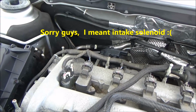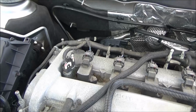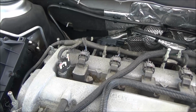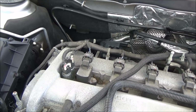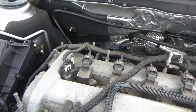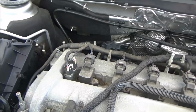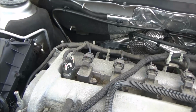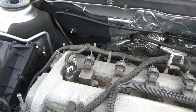So some things I can tell you about these solenoids off the top of my head. Both of these wires go back to the engine computer. I know for a fact from testing these in the past that they are power side switched and they are duty cycled. They are not going to be duty cycled all the time. They're just going to be duty cycled periodically, and obviously the engine computer is controlling them directly. So a couple different ways we can attack this, guys. We can check for control at these solenoids.